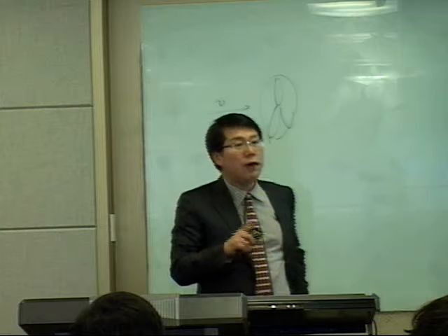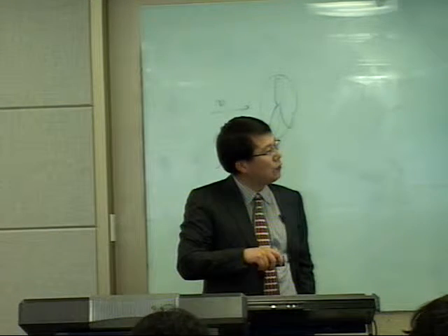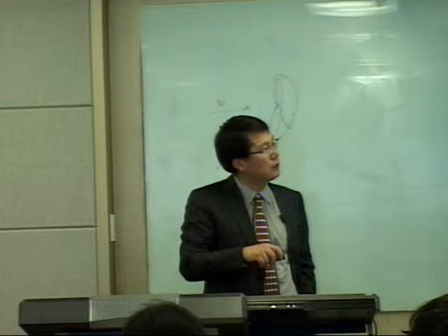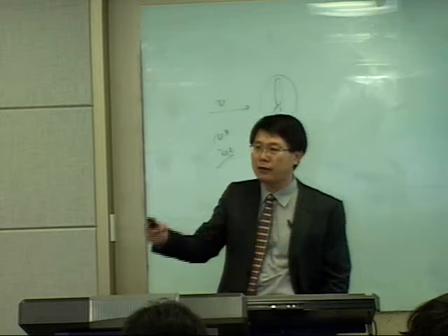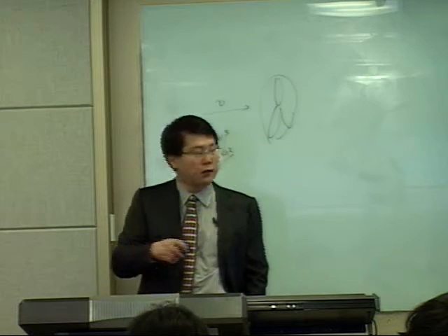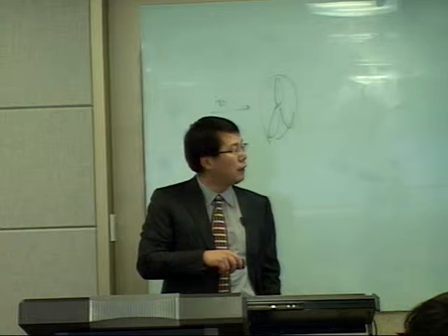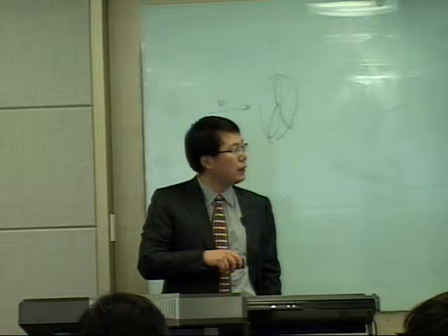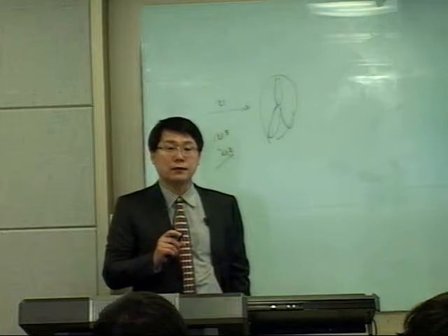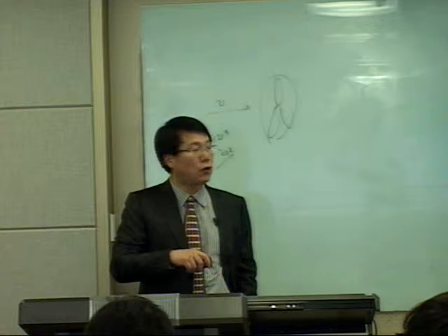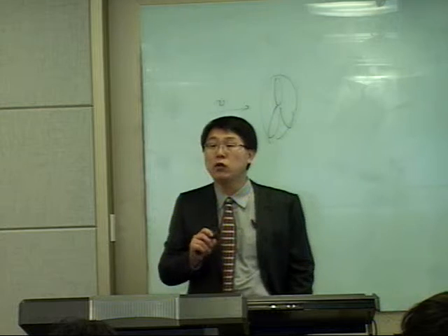So the mass flux on this surface is delta y delta z rho Vx minus the mass flow rate on the opposite side, rho Vx at x plus delta x, and delta x delta y delta z times rho is the total mass within the cube. So this term is mass change within the cube.